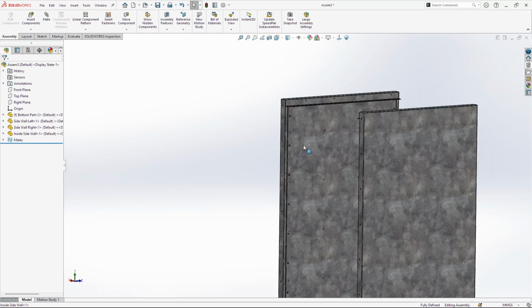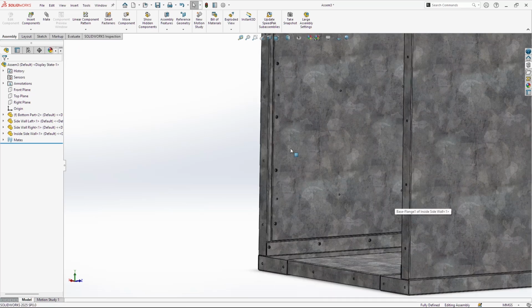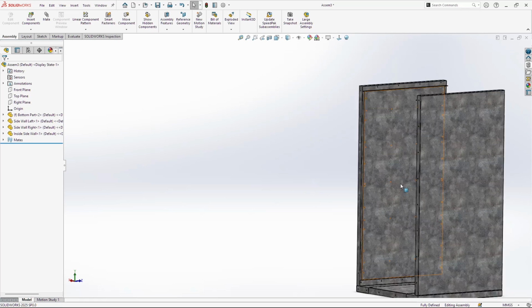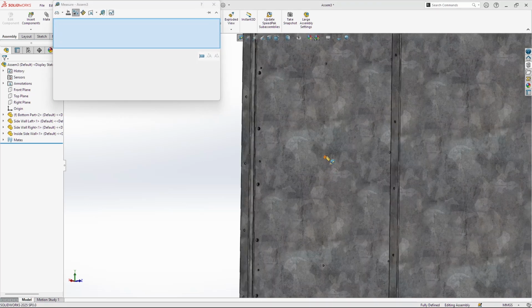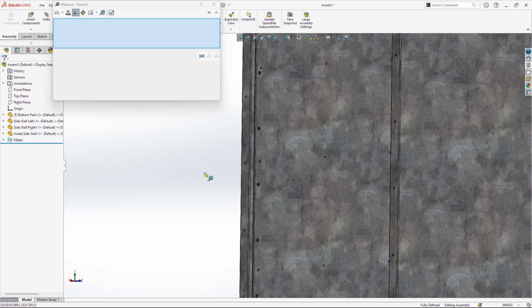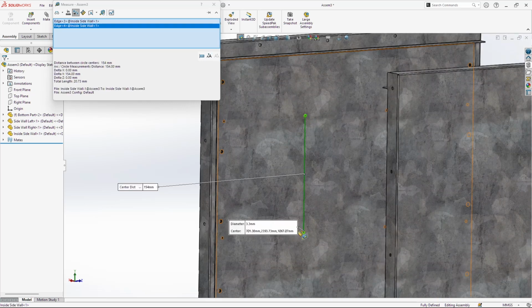The top side is going to be the side where the gap from the holes are smaller, and the bottom side is going to be the side where the gap between the holes are a little bit bigger. Bigger gap between these small holes here. Bottom is 179 and top is going to be 154 millimeters.